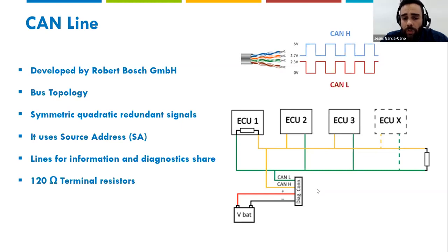If the measurement is 60 ohms, the resistance is okay. Why 60 ohms? Because in a parallel circuit, the total resistance is the inverse of the sum of the inverse resistances.